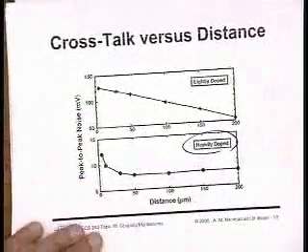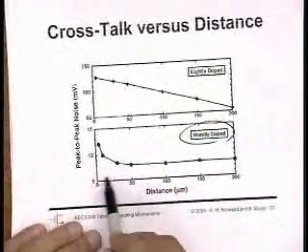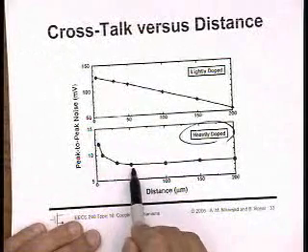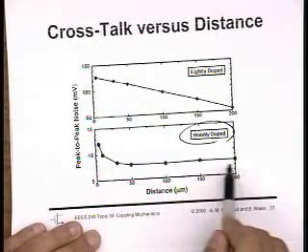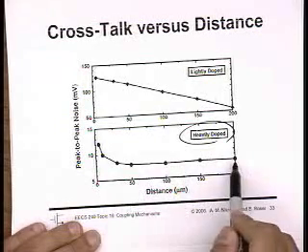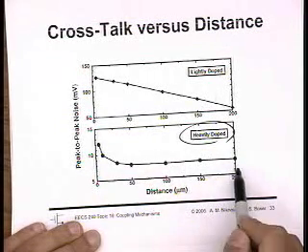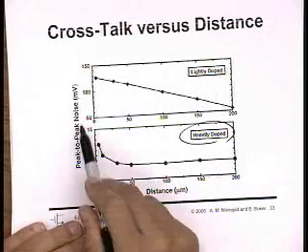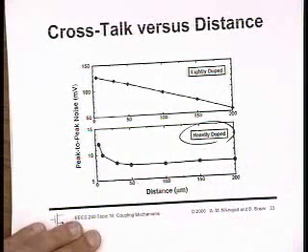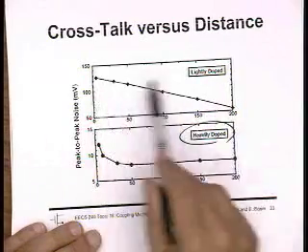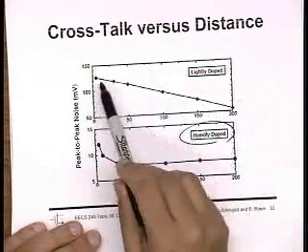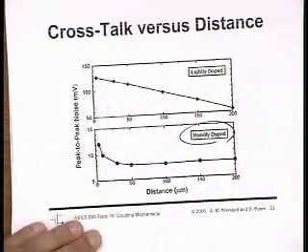For a heavily doped substrate down here, you can see that as long as the distance gets to a certain critical threshold, then it really doesn't matter. I can go from 50 microns to 200 microns, and the peak-to-peak noise voltage that I'm picking up is practically the same, right? And on the other hand, with a lightly doped substrate, you see distance matters. So as I increase the distance, I see almost a linear drop in the noise pickup.